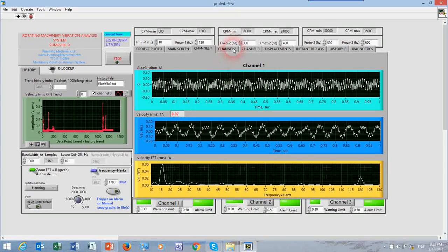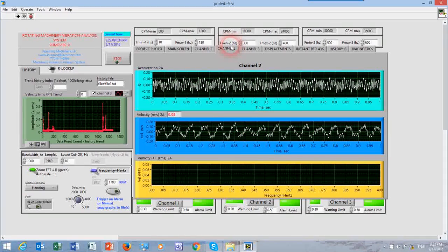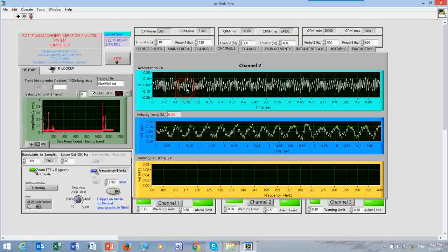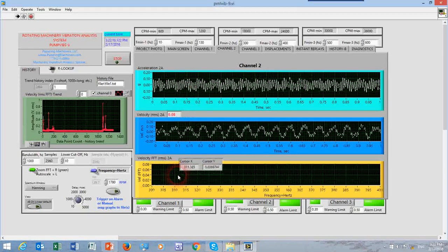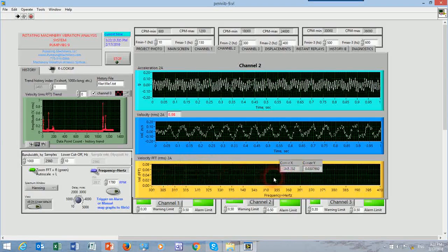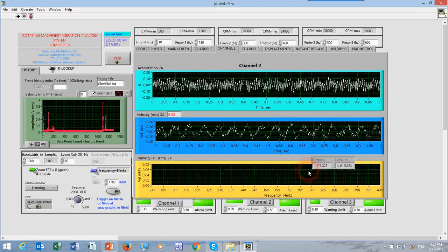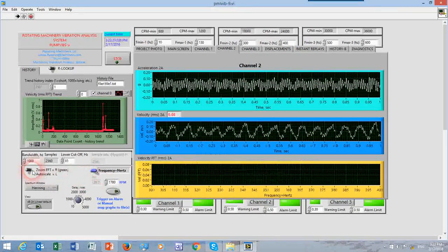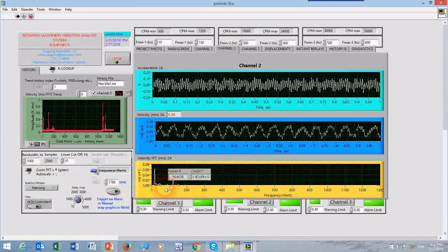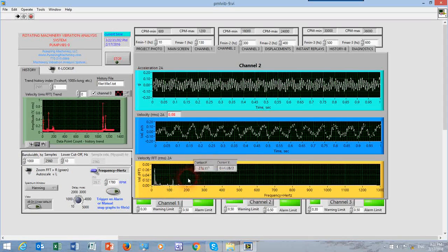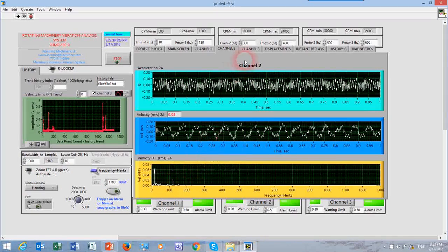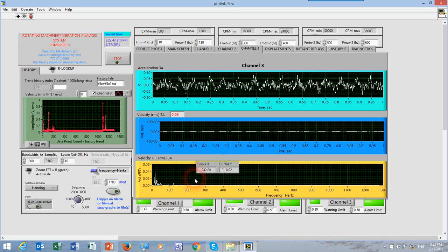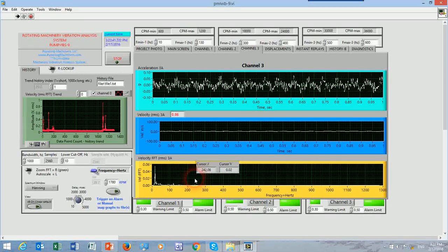So channel number 2 is similar. It has 0.08 RMS velocity, and of course acceleration, velocity, and amplitudes are shown below. Nothing shows on the bottom chart. Why? Because it happens to be zoomed from 300 to 400 hertz, and nothing happens there. Let me unzoom to get the entire spectrum, and now of course we see the 16 and 120 spikes back in action. Channel number 3 likewise shows acceleration, velocity, and velocity spectrum FFT analysis.